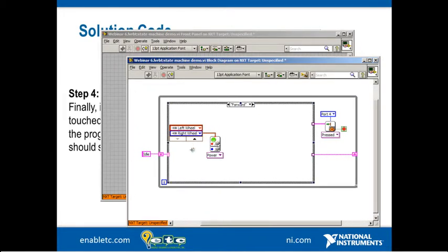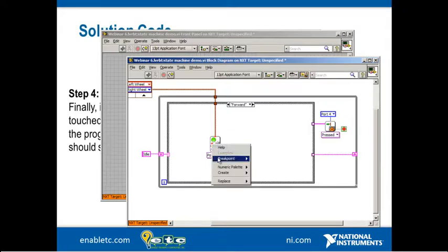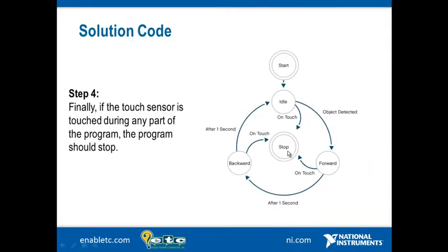We've seen this trick in previous webinars that we know we're going to use this motor constant somewhere else, so we can drag it outside of our while loop so it can be used just by wiring it in. We rewire up into our move DC motors function. Now we just have to give it some speed values. So we're going to right click to create constants because we want to move forward. We're going to give them both the same speed, and in this case it doesn't really matter what the speed is, we'll just give it a value of 50. Okay. Return back to our state diagram, take a look.